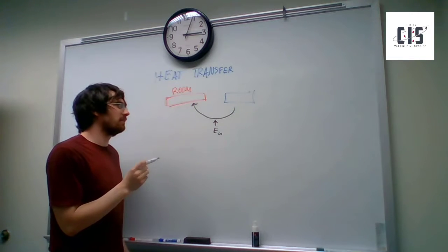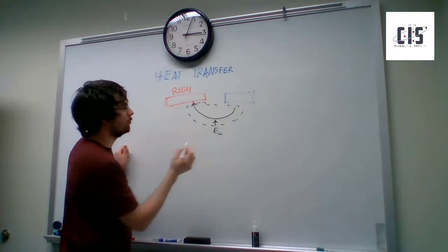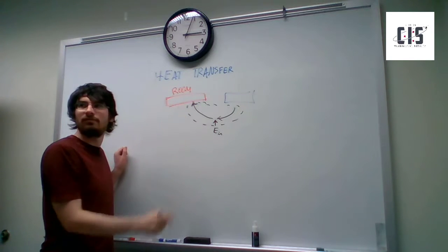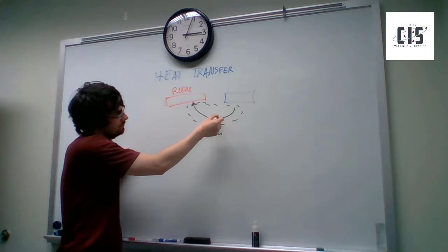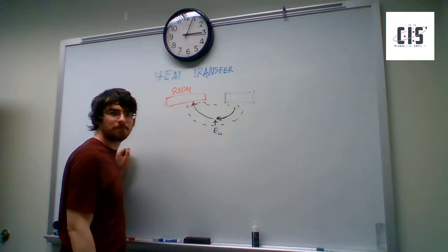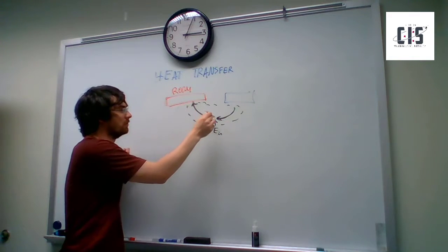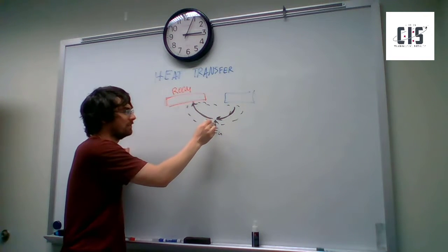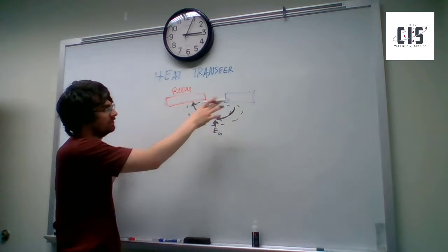But the important thing is that since energy is conserved in here, what can you tell me about this amount of energy? It's going to be much higher than the energy that would be cooling the space. Yeah, so it's higher. So more goes to the room than inside the refrigerator. Yes. In fact, the amount of energy here is equal to this plus this. Oh, so half. Yeah, because you're removing heat energy from here, and then you're adding electrical energy. So it's not actually half, but it's a sum of the two, basically.